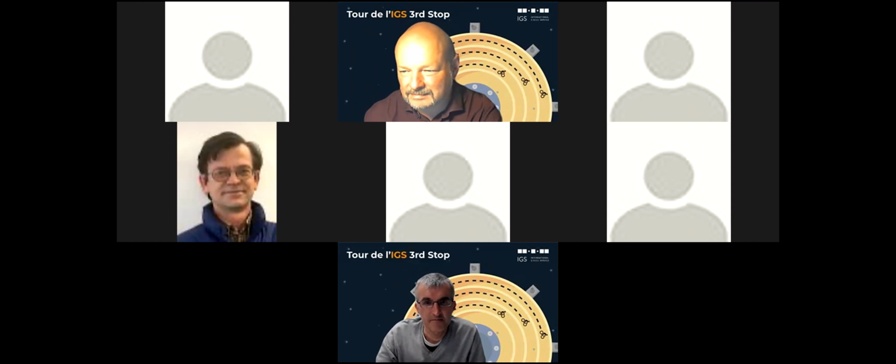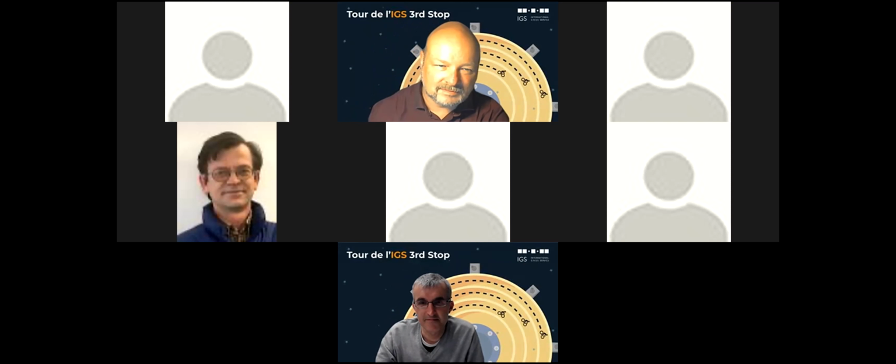If I use a uniform weighting strategy for my observations, I will get that a wrong mapping function will generate an error in the height and the tropospheric estimation. If I use a weighting strategy that weights too much the zenithal observation, I will have the opposite effect. And my estimation will be poor. So is there, from you experts, a weighting strategy that I can use, that is suggested by you, to be applied for retrieving tropospheric delays?